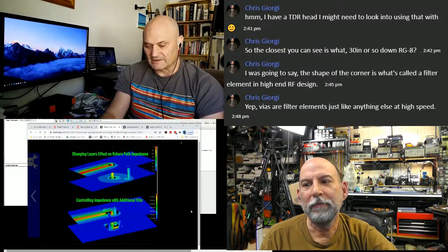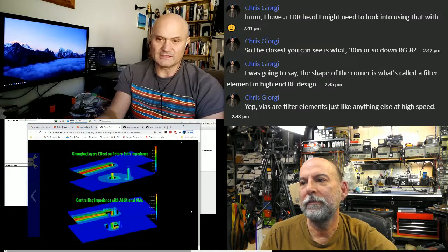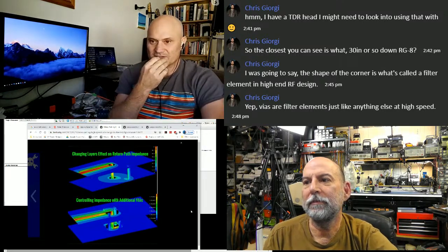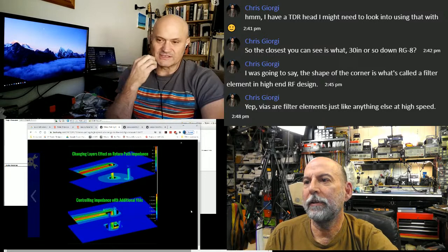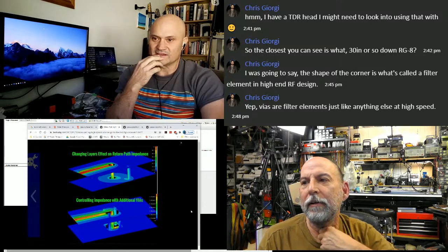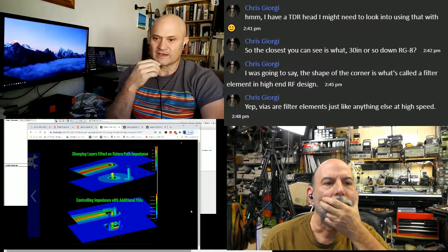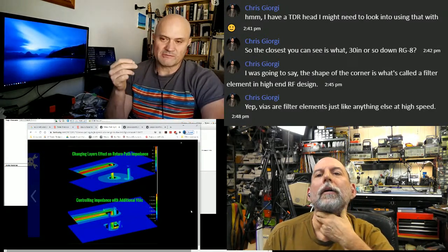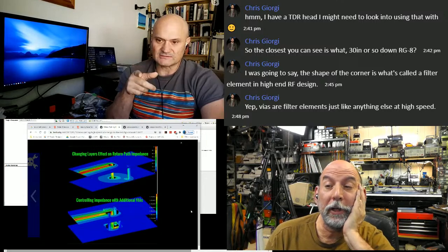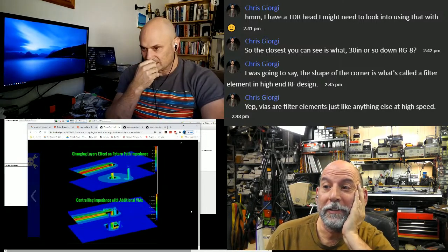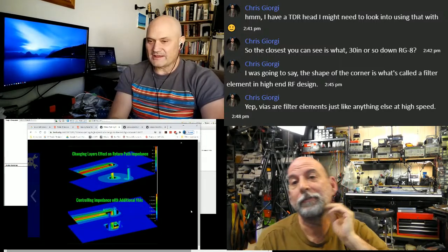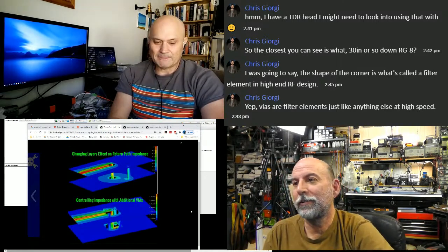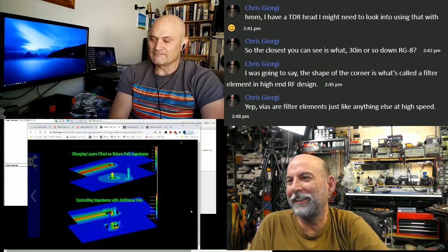What they didn't realize back then in the 90s, and it wasn't until as recent as 2008, that I started seeing scholarly articles about people actually maintaining signal integrity by experimenting with return path vias. We used to split the ground planes. Oh, yeah, that got out of fashion when people realized... Back in the 90s.